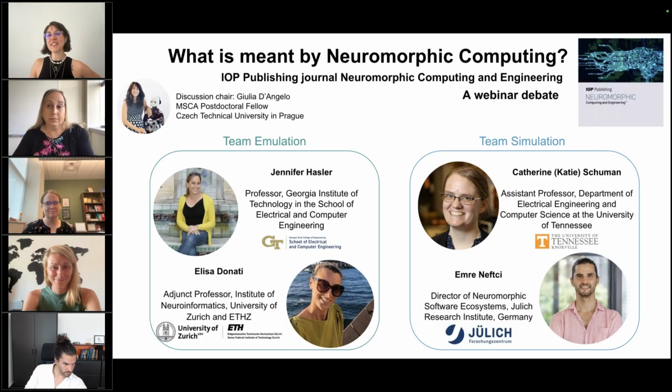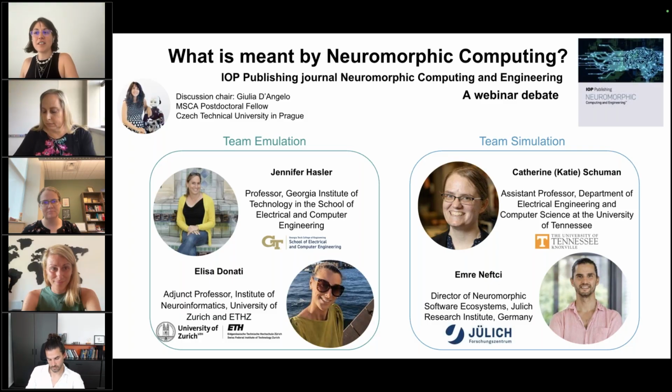Can I go? Okay, so this is for team emulation. How do you reconcile a need for scalability with the need for neurons and synapses to each be physically instantiated in an emulation system? Simulation digital systems are easier to scale by multiplexing neurons over the physical substrate. Do you think it will be possible to deploy emulation mode analog systems at volume without needing on-device adaptation or learning? I'm thinking about the uncontrolled device mismatch across devices and between chips.